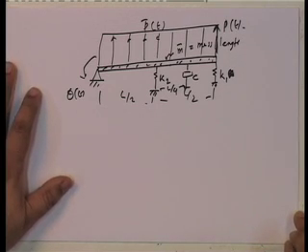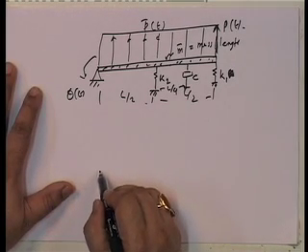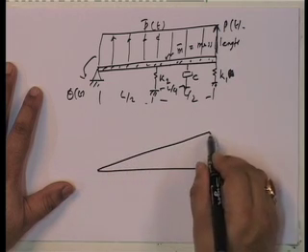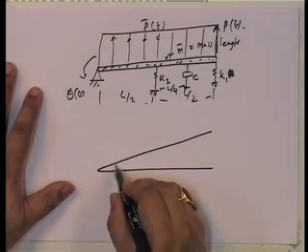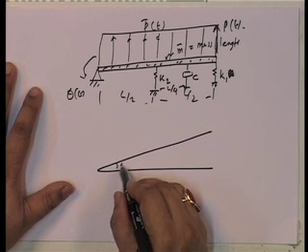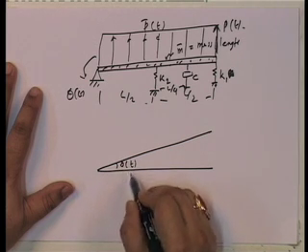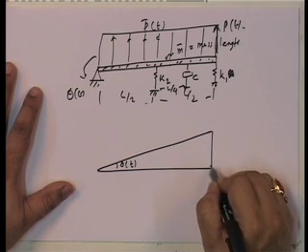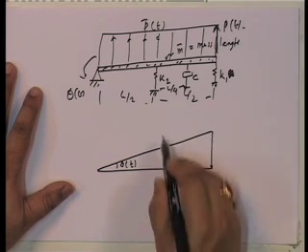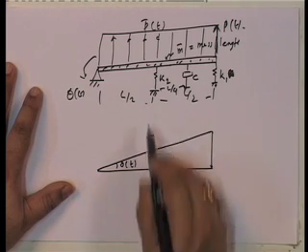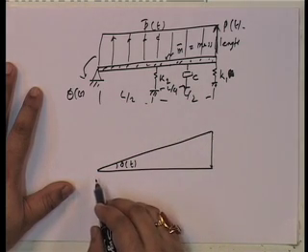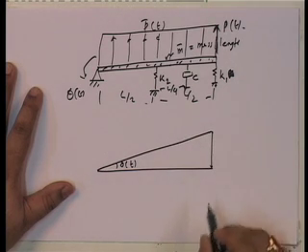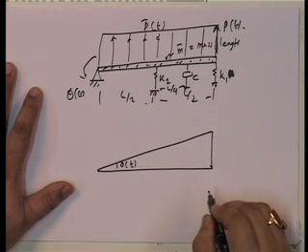So, the first thing to do is what? Displacement. Note that although I draw it very large, every point only moves along the tangent, because remember, small displacement means the arc and the tangent are the same. That is the fundamental point.